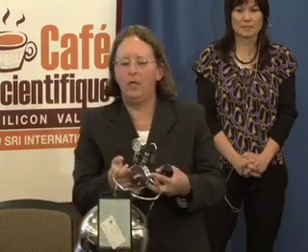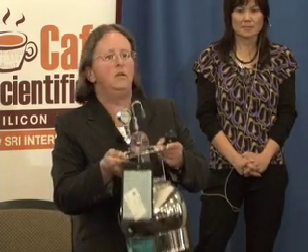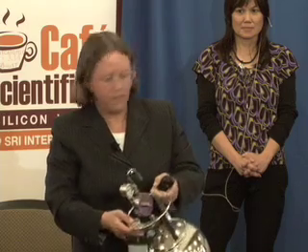If we're sampling in commercial or industrial areas, we'll typically sample over a typical workday. It might be an 8 or 10-hour workday. For residential sampling, we'll typically set the flow controller so it fills over 24 hours. So we'll meet with the residents, set this up on a coffee table, start it running, and then come back about 24 hours later and pick it up. Then we send it to the lab, and what they have is a whole air sample.